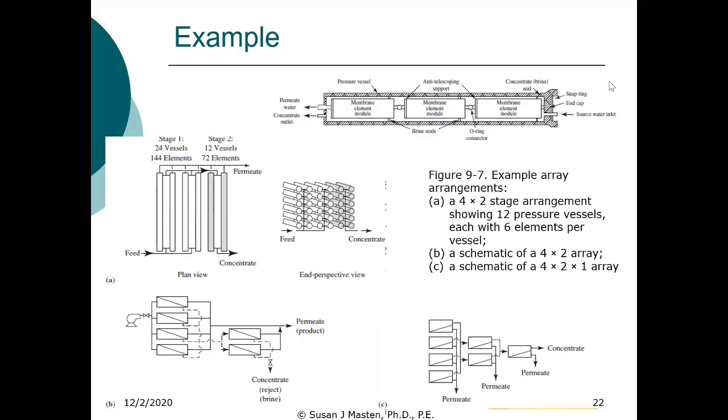And what you see here, and let's just look at the end perspective, are, again, light granular filtration membranes. Notice that the plumbing is such that for each membrane unit, you've got these two membranes plumbed like this. Again, it's just cheaper to plumb these membranes. The piping is expensive. So if we can minimize piping, we want to do so.